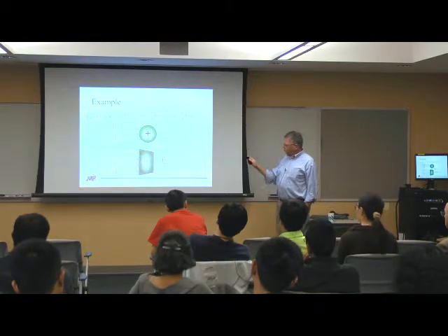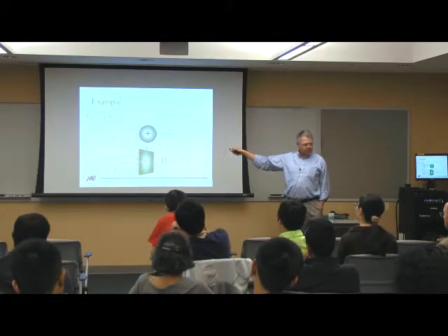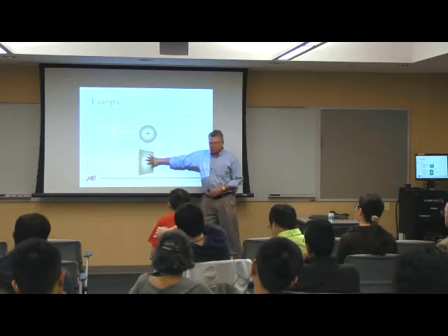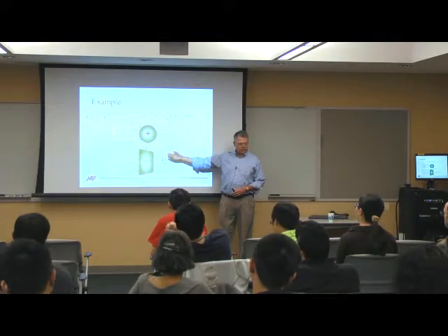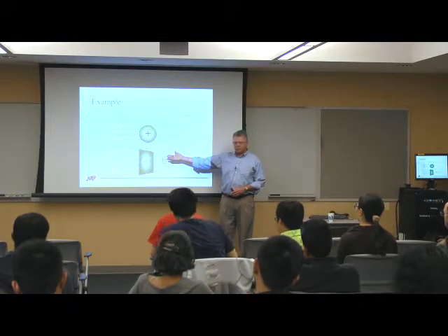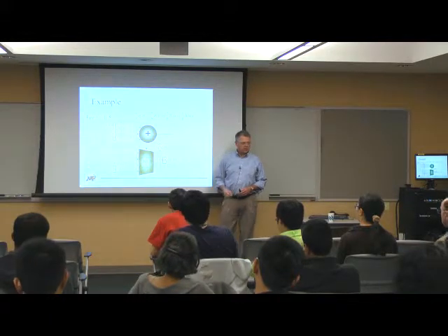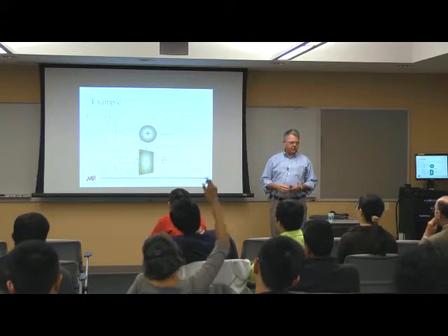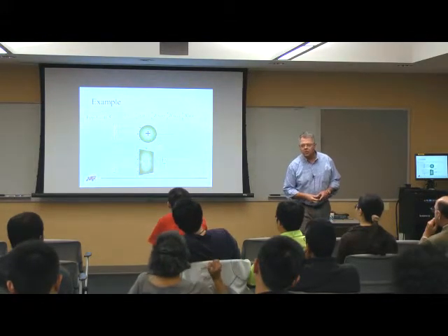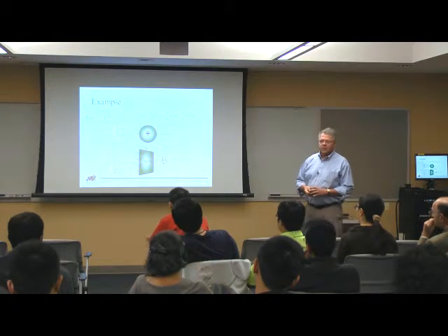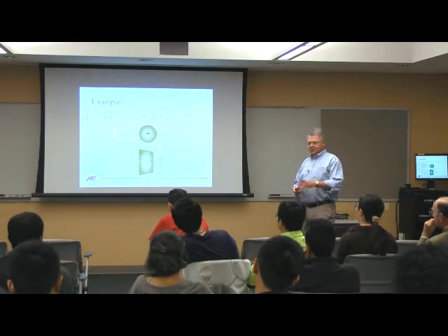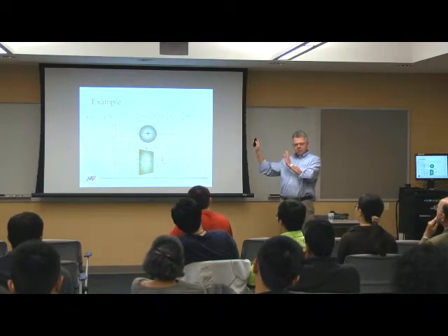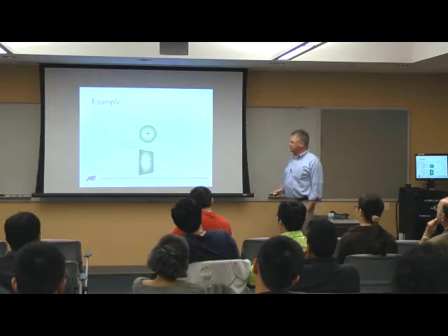Okay, and that's one of the key weaknesses here, is how many bits do I need to do this? It turns out that it doesn't matter if I do this replication in time or if I do it in space. I can do all of these bits in parallel and just pay more hardware to do that. So I can reduce the latency as far as I want just by paying for more hardware to do that. But we'll see some of the trade-offs here. So then if you pay for more hardware, how does it compare with conventional? Yeah, very good question. And I'll get to some results later with some of those comparisons. Right now I just want you to get the general sense of how this is working.